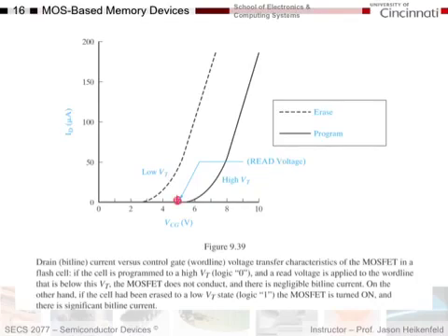So I put that on the outermost portion of the gate, and if I had set the charge inside that floating gate such that the threshold voltage is lowered, then when I put my read voltage, I will get current out. So this would be a logic 1. If I put the charge on the floating gate such that it increases the threshold voltage, and then I do my readout voltage, my current, you can see, is 0. And so that would be a logic 0.